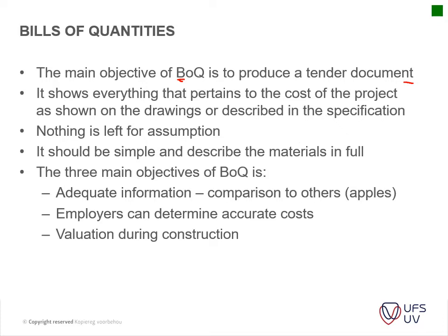So your first fix is usually your pipe work, chasing in through walls and so forth, whereas your second fix will be your sanitary fittings, where you get your toilets being installed, your baths, your hand wash basins, etc. So although it follows a logical flow, it doesn't follow exactly according to the program. So just bear that in mind.